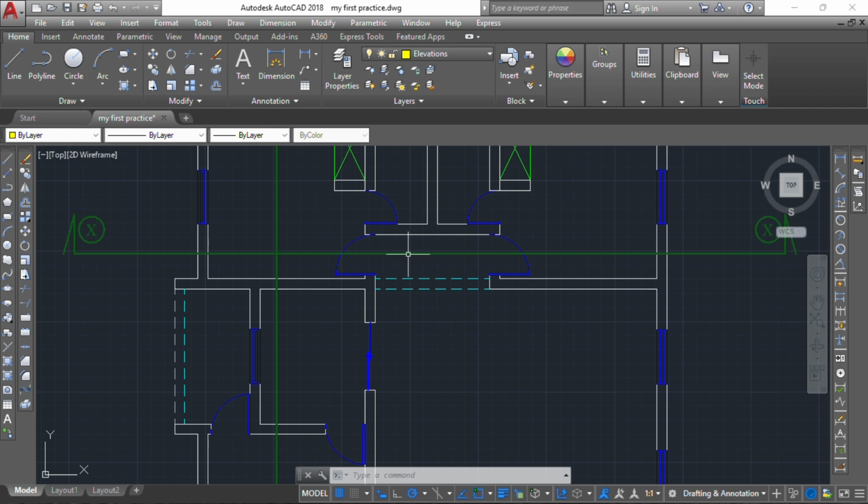Apart from that, any window or door we are cutting across will have a lintel above it. In real life construction, when you create the spacing for your door and your window, and you want to continue laying the extra courses of block above, you have to cover the sill of your window and door with a lintel.